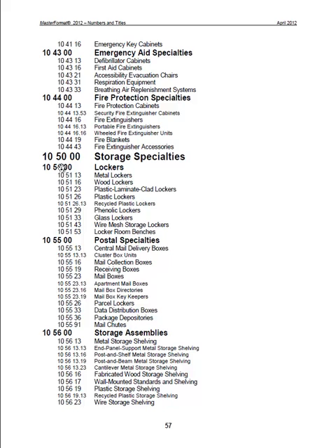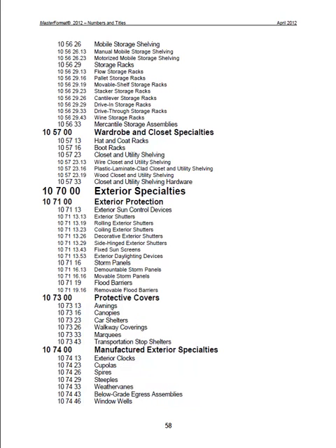Your lockers in your locker rooms have their own special section, 105100, and you can break it down into metal, wood, plastic, phenolic, glass, wire mesh, all listed in here. Many of these can be found online as far as the specs go from particular manufacturers. I'll show you how to do that shortly.